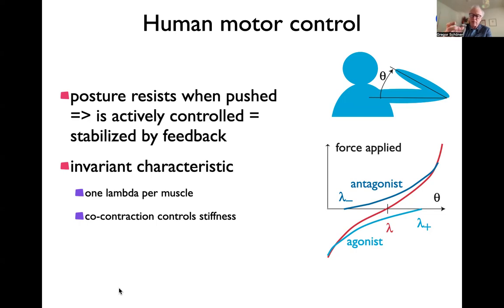You just plan a configuration of your fingers inside the object, and that will mean that the springs' equilibrium position is inside the object. And as the object resists, the springs press against the object, but they only press with the force that the spring exerts, depending on how stiff it is, and that can be just right to grasp it, but not enough to break it. And you control that. There are some deployed systems like that, but this is work in progress.